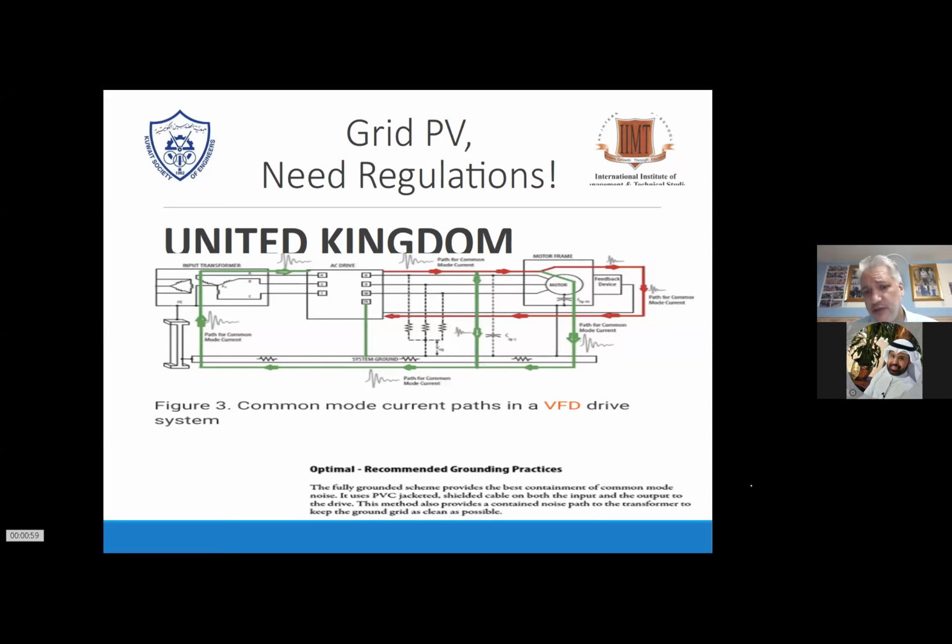With the VFD drives, mostly it was 35 to 50 millimeter. With an inverter, it could be 6 or 16 millimeter. That's fine. So just think about it: if you encounter problems, the first thing you should do is earth a second one, but you should have done it in the first place already. So earth the chassis of the inverter if it's possible.